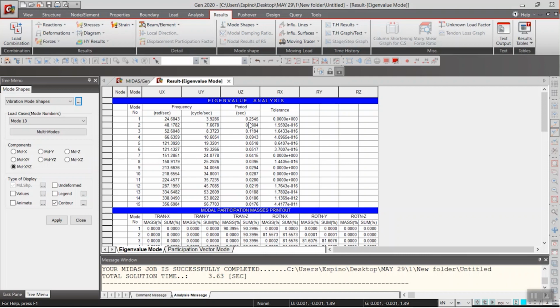So approximately around 0.1 to 0.5 seconds, if we have this period in our floor structural system, if we are in the range of 0.1 to 0.5, we can call it, I don't want to use the term safe, I can use the term within the acceptable limit.